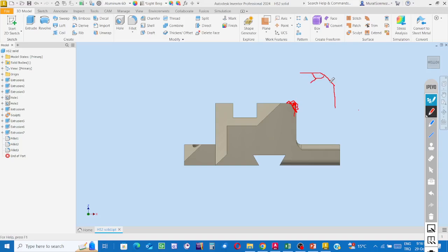If the sharpness angle is greater than 90, you see these are obtuse angles, then this means the hand cutting risk will be less. That is the motivation, that is the logic in creating a chamfer. A chamfer is an inclined flat surface. It extends along an edge. It is to prevent possible hand cuttings. It is a cheaper solution relative to the cost of the rounding process.